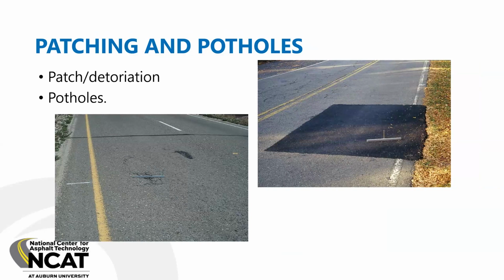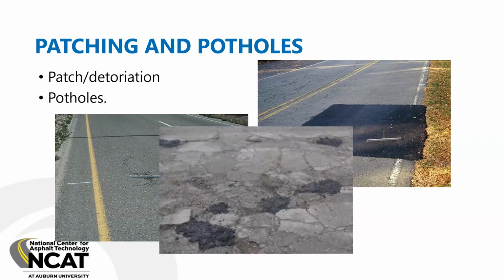What you see in that picture actually looks like an area of local debonding and slipping. And then when that comes apart, it's a pothole that originates within the pavement structure at the area where the slip occurred. Potholes can also occur because of soft bases and soft subgrades and water and all types of things like that. But this actually looks like debonding is what caused that.